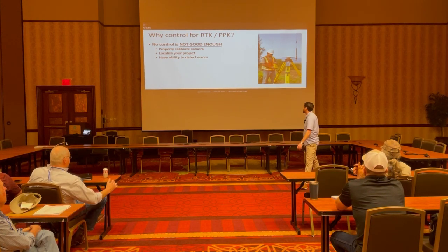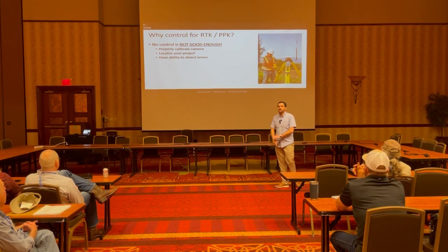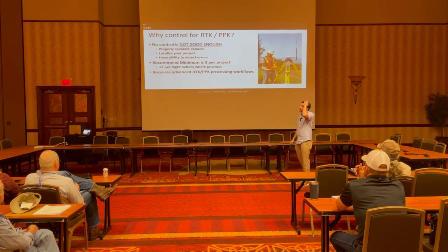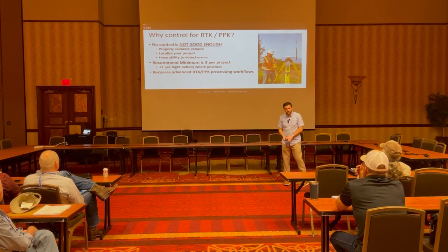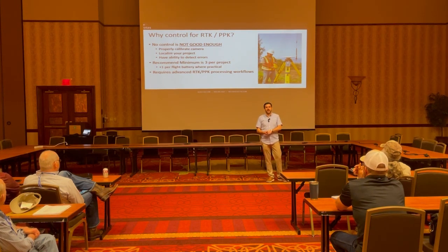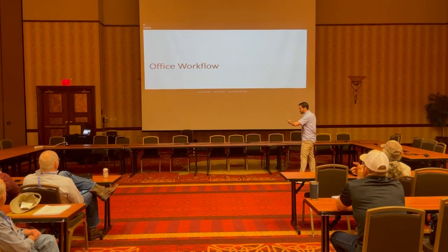So that's something that's very common with us and part of why we really, really like having control and think that some level of ground data is necessary, even with RTK, even with PPK, even with all of that. The cost of having a perfectly reliable, no ground data workflow is exceptional, and the risks are very high as well. So we don't like doing no ground control.